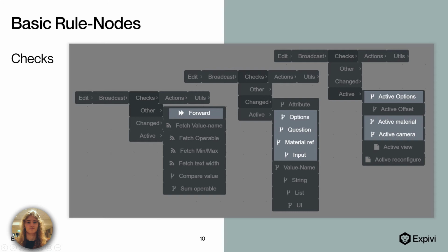The changed option node. When the check option node receives a signal, it checks if the specified option was the cause of the signal. This is useful for very deliberate choices that don't need to have a continuous effect. For example, choosing a desk width of 1 meter should also automatically select a privacy screen of 1 meter wide, more like a suggestion. After the screen has been forcibly changed to a meter width, the user can still change it back if they prefer something else. When using the active option check, it would force the width change every time an option changes, effectively removing any choice for the screen.